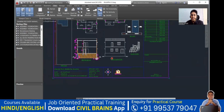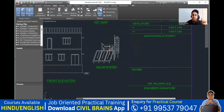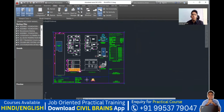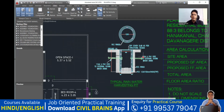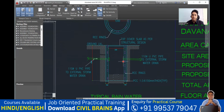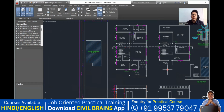They have given a small solar system here. Maybe at the top they are going to keep a solar system, so they have drawn it here, and they are going to install it at the top of the parapet. And then this is of course the typical rainwater harvesting pit, the same thing we understood in the previous lecture. You have a ground level, then you put a borewell here, and these are the RCC rings, and this is a PCC, and those pipes you are going to put. In this way all the drawings will be prepared, and based on that you are going to do the construction.